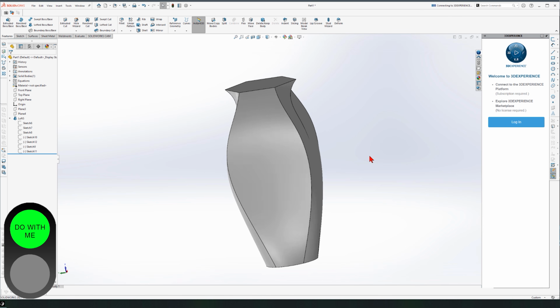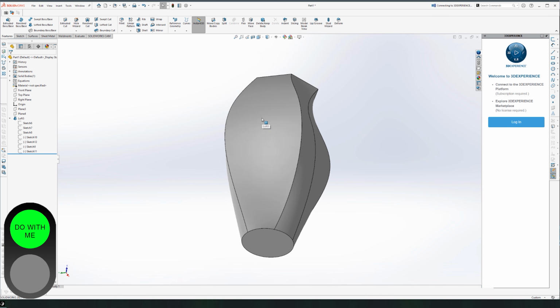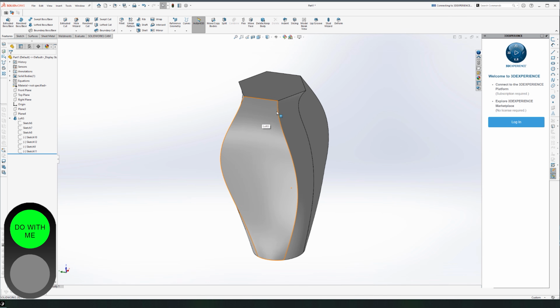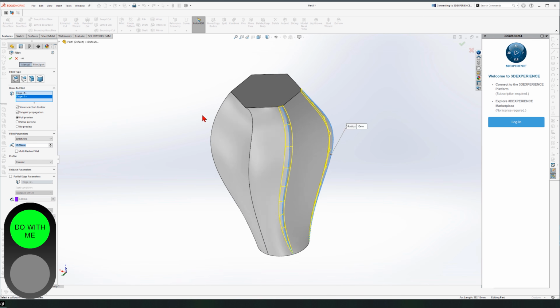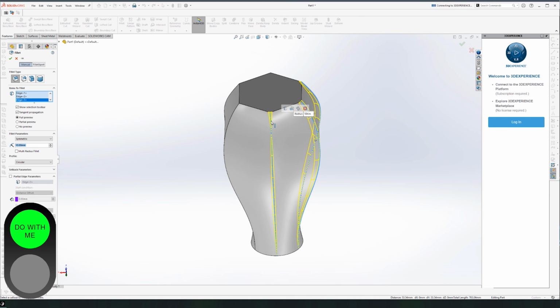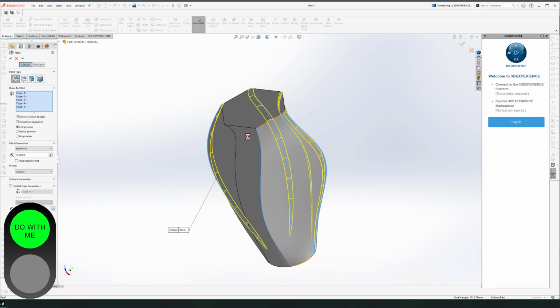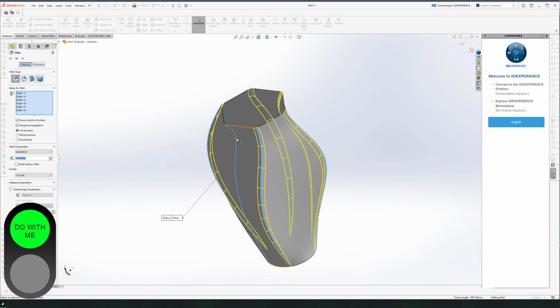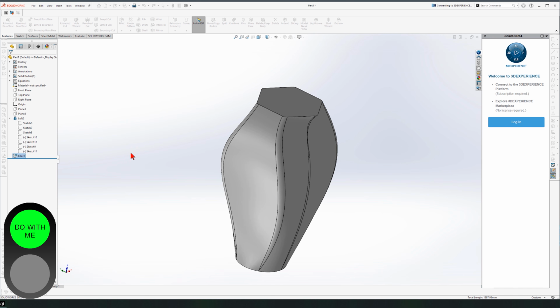Sharp edges, do you want to get rid of that? You can, if you want. Do we want to do that? Using fillet, we can. Click, fillet. Select the next edge. Select the next edge. My bad. This edge, very bad. This one, and this one. With the value of 10, click OK.